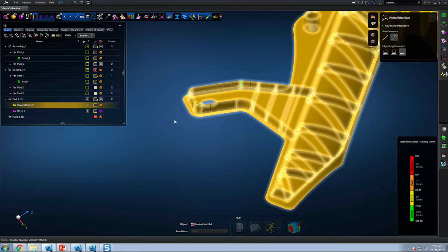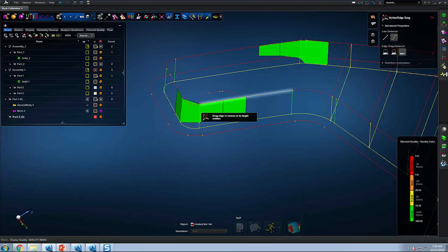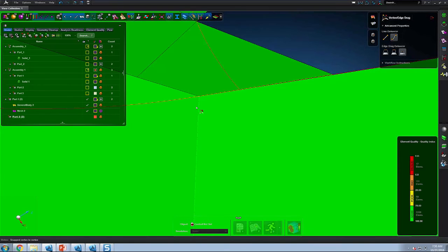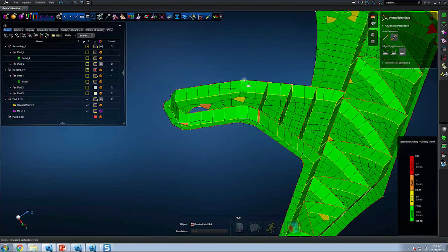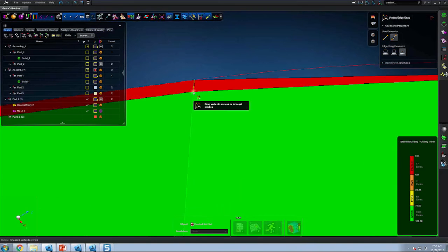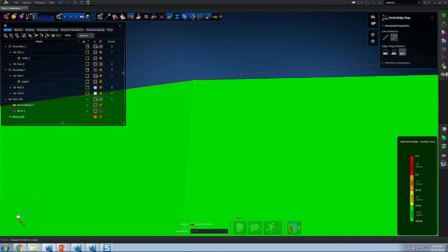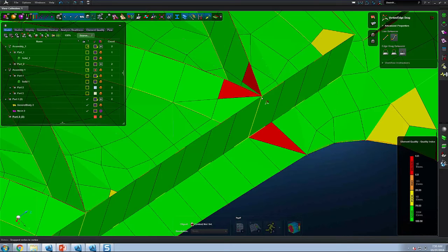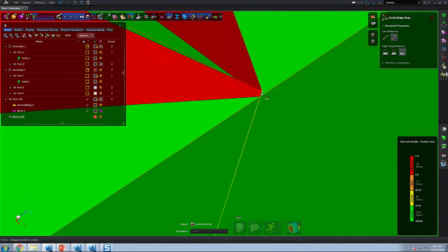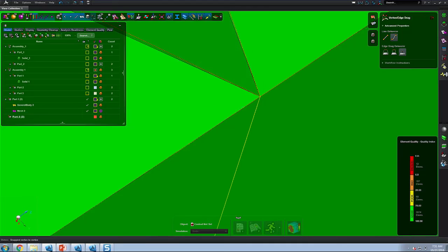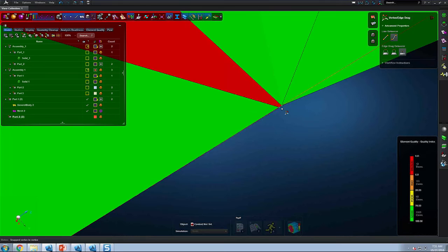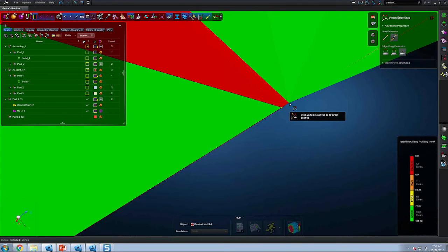That's number one. Number two, after finding regions that are problematic, I can go in with the same tool you saw a moment ago, and I can drag a vertex. Once I drag a vertex here, the mesh is automatically updated for me. I didn't have to delete the mesh, perform a geometry edit, then recreate the mesh. Here, as you see the tool, it's just a matter of me going to the actual spot, making the edit, and the application automatically creates the edit for me. And this is really handy. Again, another big time saver for you.